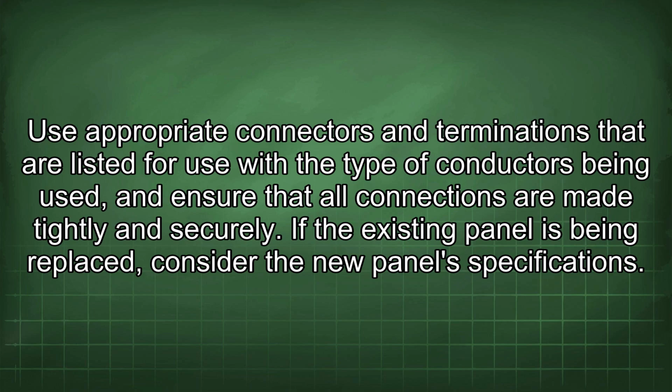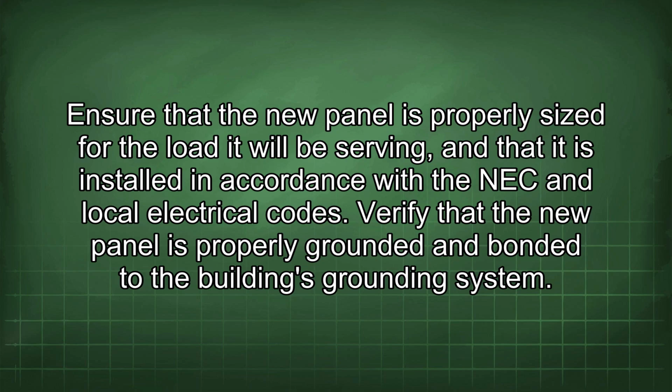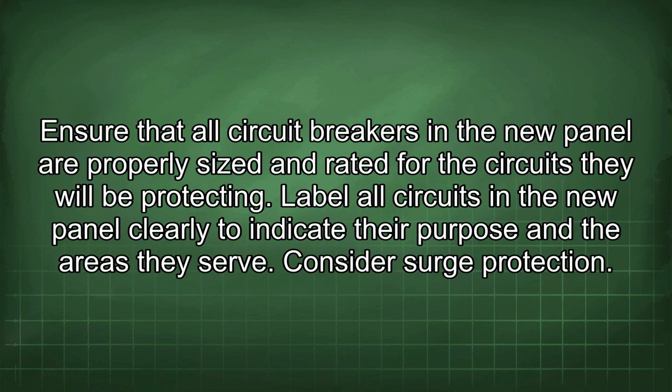If the existing panel is being replaced, consider the new panel specifications. Ensure that the new panel is properly sized for the load it will be serving and that it is installed in accordance with NEC and local electrical codes. Verify that the new panel is properly grounded and bonded to the building's grounding system. Ensure that all circuit breakers in the new panel are properly sized and rated for the circuits they will be protecting. Label all circuits in the new panel clearly to indicate their purpose and the areas they serve.